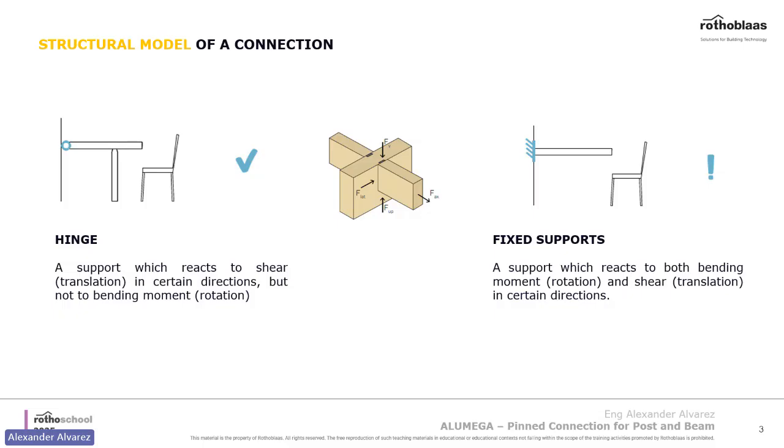You can stick the wood inside of it, but then you start thinking, this might not be a good idea, or it might be too expensive or too complicated. That's why some engineers prefer pin connections. It's pretty simple, and to deal with the rotation and the moment, there's another system in play to deal with those types of forces.